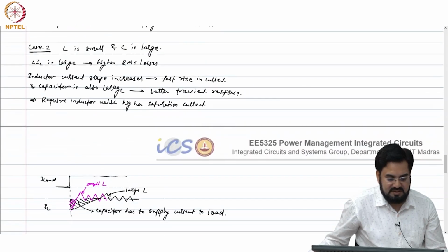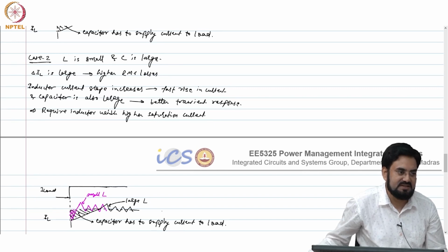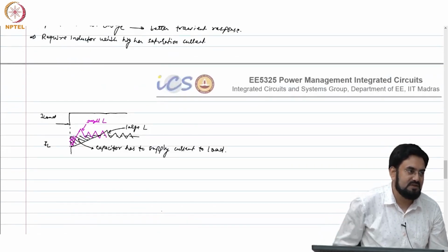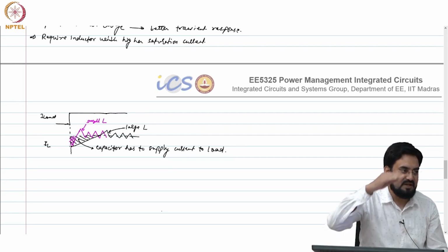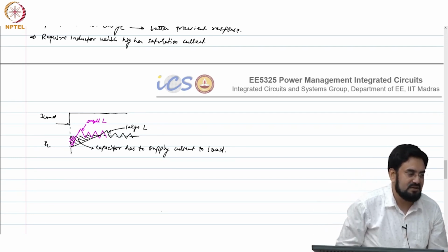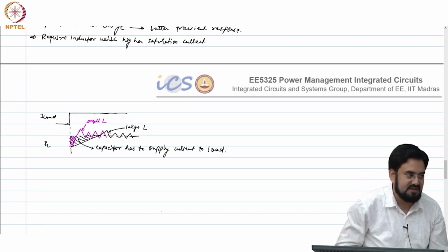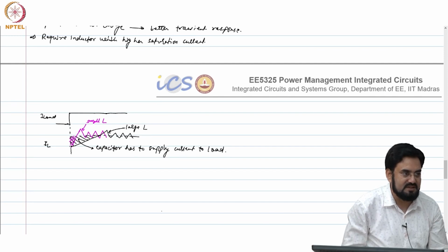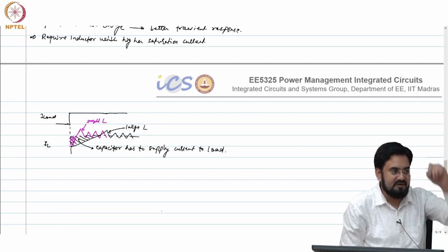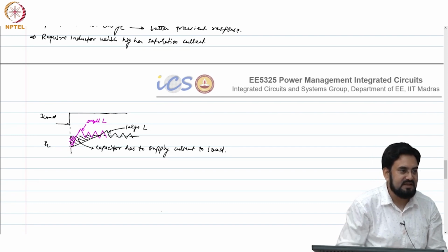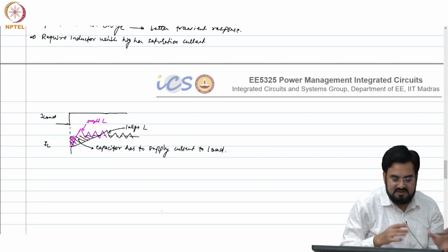Okay. So usually saturation of an inductor is defined when the value falls 30% below your typical value. So if you are using 1 microhenry and the current at which it goes to 0.7 microhenry, that defines the saturation current. That is soft saturation, but there is something called hard saturation also, where the inductance will fall very quickly. In that case, that is defined almost like 0.9 or so. Okay. So it depends on the type of inductor.